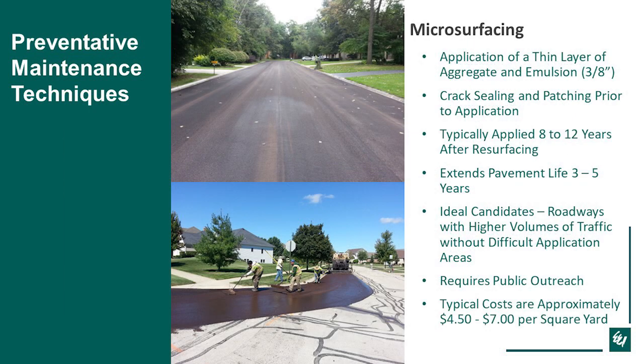Microsurfacing, it's another preventative maintenance option. It's typically done around the 8 to 12 year mark. You're going to want to crack seal and do any patching prior to doing this microsurfacing. It's an application of a thin layer of emulsion on the road.